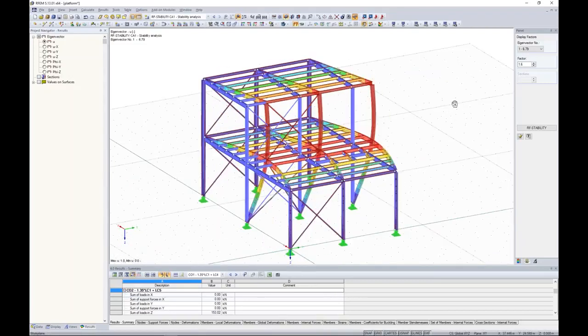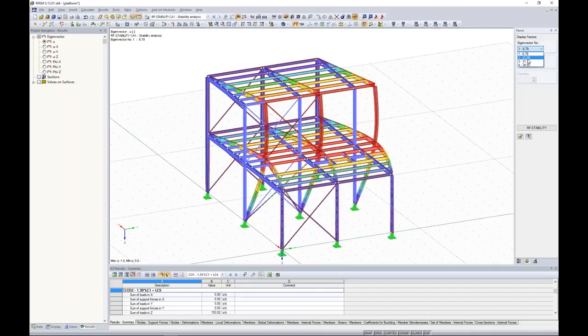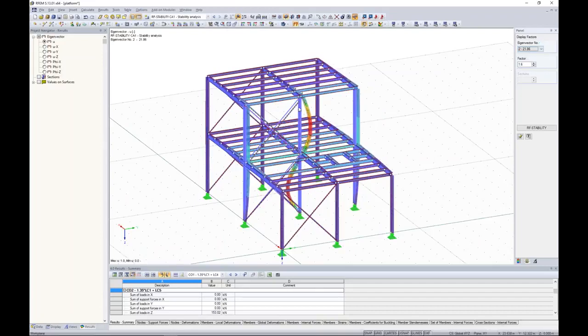If this value is above 10, like the second one, where we have a buckling of the inner column, then it would be okay just to calculate according to first order theory on the undeformed shape, because the bending moments won't change according to second order, and it's fine for first order calculation.